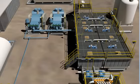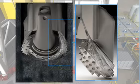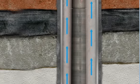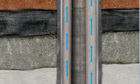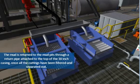The mud is mixed and taken from mud tanks, pits, before being pumped down the drill string. It exits the drill string through holes or jets situated in the drill bit. The mud then returns to the surface via the space between the outside of the drill string and the open hole or casing. This space is called the annulus. The mud is returned to the mud pits through a return pipe attached to the top of the 30-inch casing once all the cuttings have been filtered and separated out.